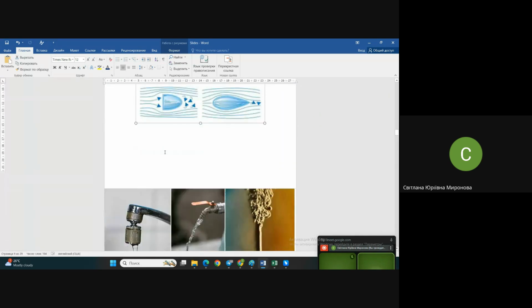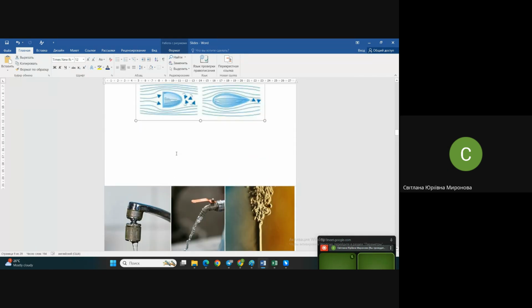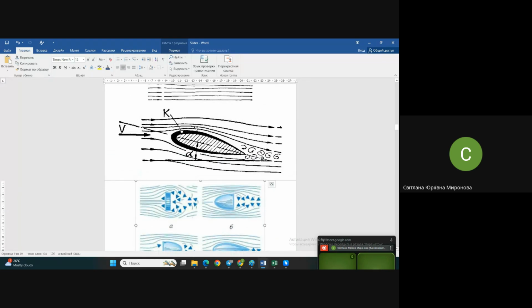And by the word about fumes, how did people actually study and see these streamlines? I said they studied it. They didn't imagine it. How? There are some ways to do it, and the most simple way, of course, is to use smoke. When it comes to gases, in front of the object a pipe with some holes is placed, and through these holes some other gas is given into the whole mass of air.